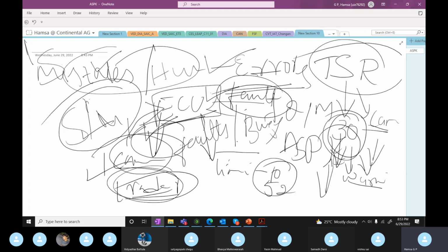Similarly, speed. Your ECU gets to know the wheel speed. Every wheel speed is different, and vehicle speed is different. So the ECU will get the input from every wheel speed sensor, which detects the wheel speed. Based on this wheel speed only, your vehicle speed will be detected. If this input is also not received, it will set a fault. These are the kinds of inputs. This type of fault is called a communication fault.